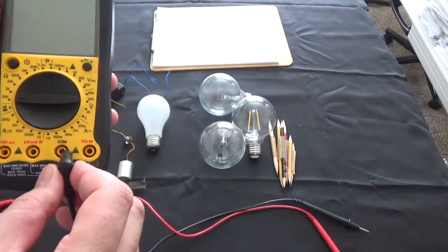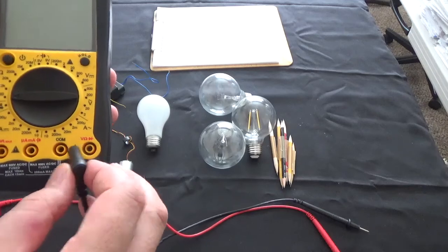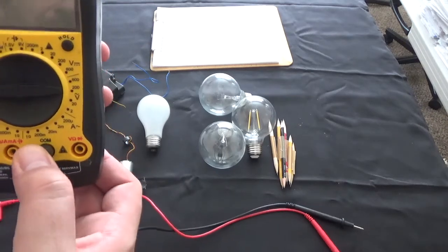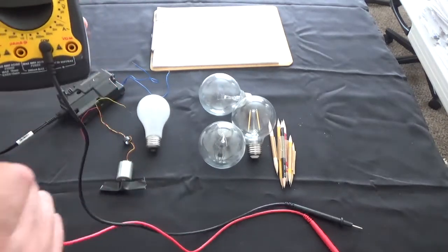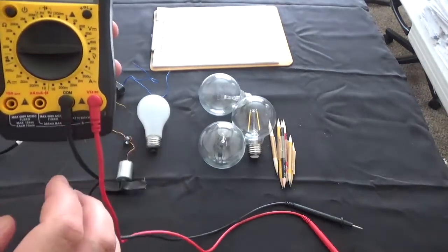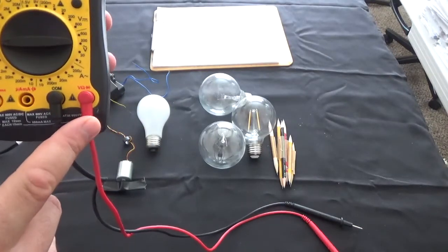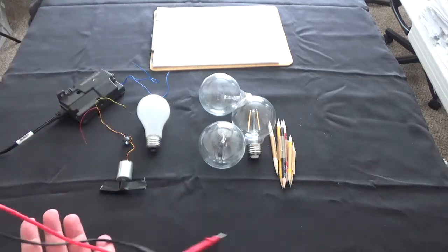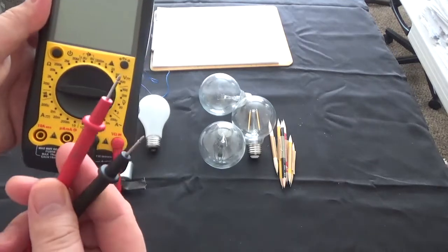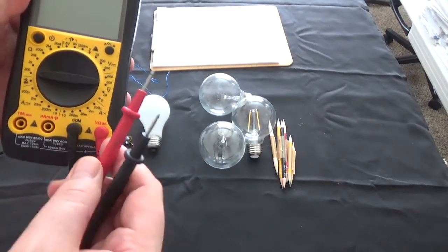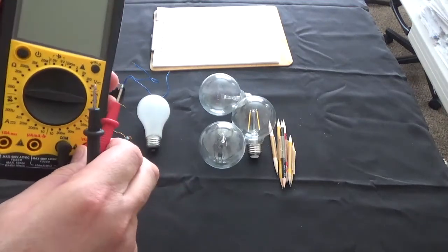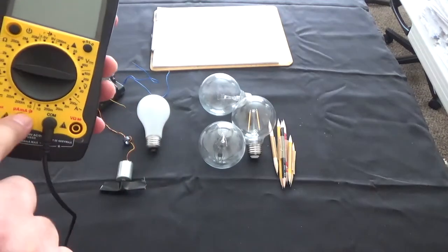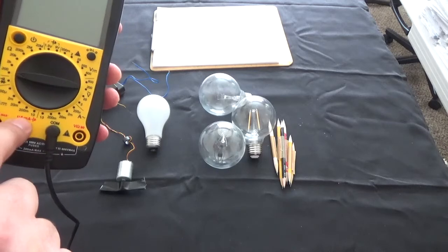The other thing that I would like to share with you: if you would like to measure the volt and resistance, you need to have those connections fixed here on this side. So now you can measure the resistance, as you can see, and volt. What if you decided to measure the ampere? Look at here. Here you have microampere, milliampere.